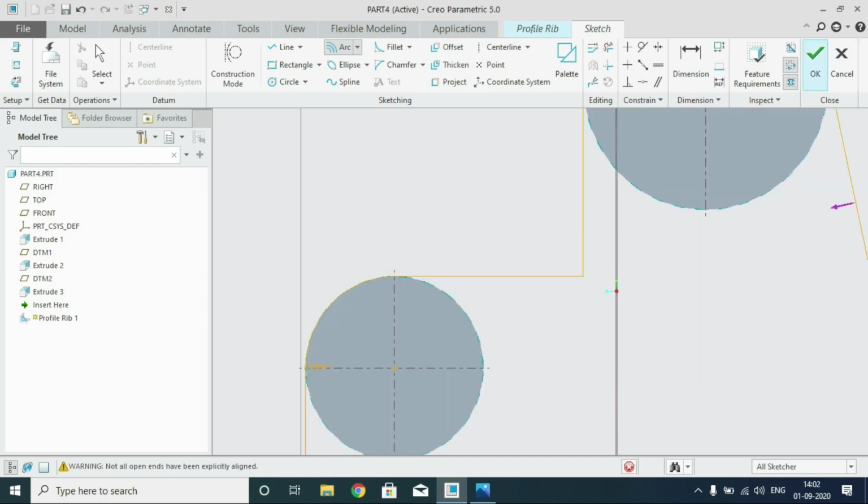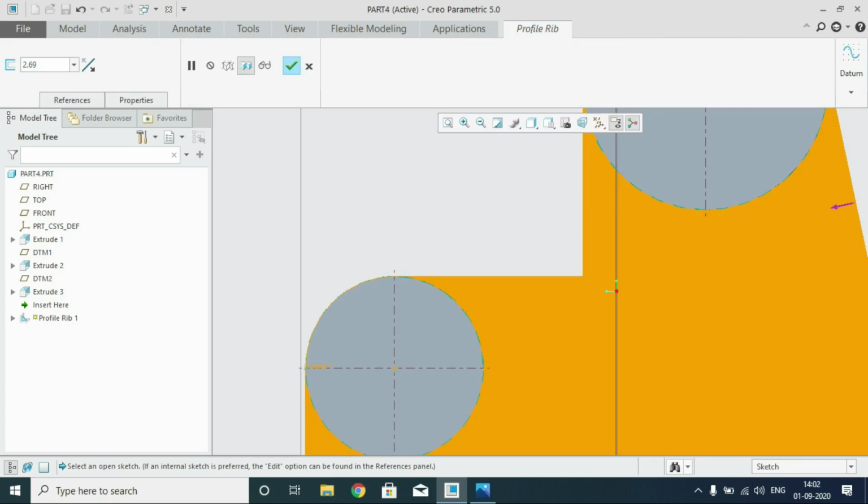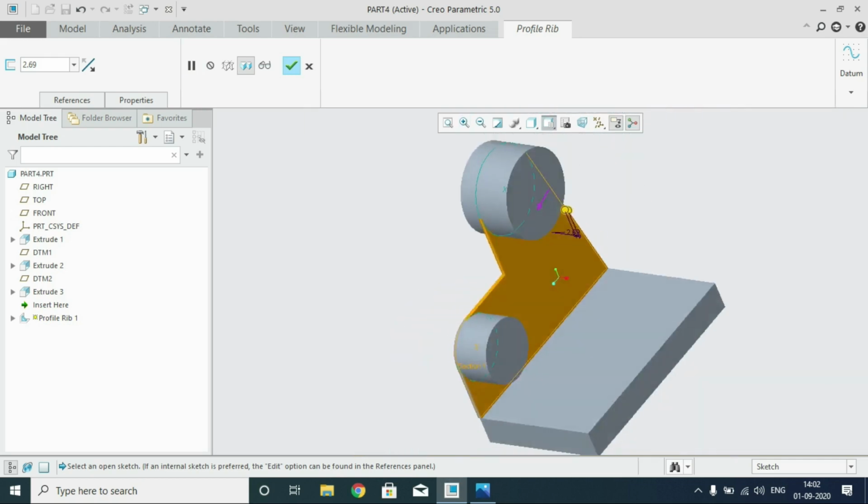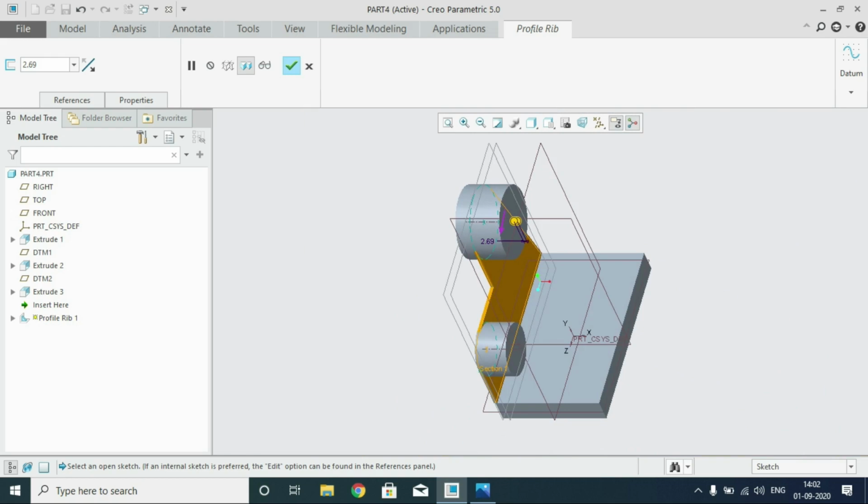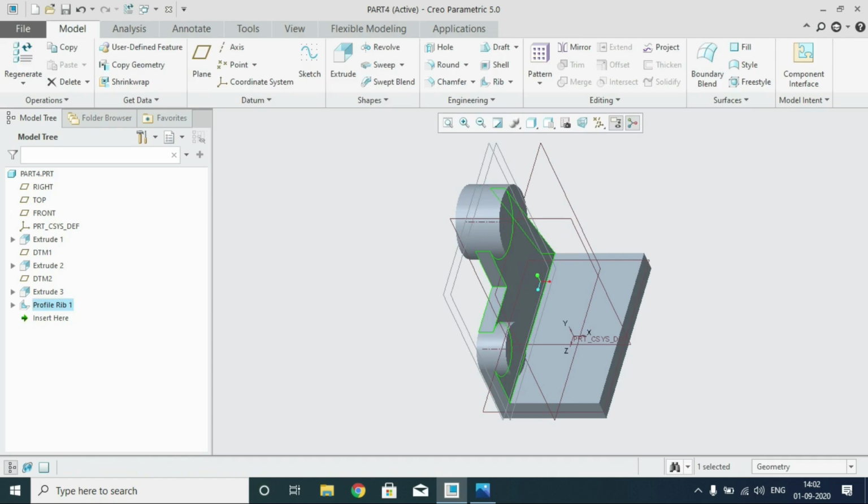Okay, you come out. You have that component out there. You can also zoom it in the default orientation, and then you can give a thickness of around 12. Now you have to change the direction. Now it is perfect. So your rib is drawn. A lot of procedures are there, so with that we are able to draw that rim.